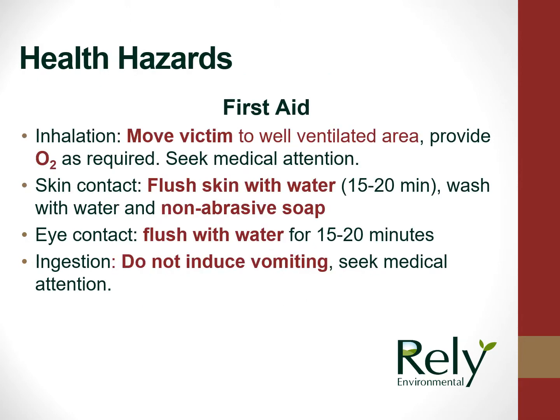If an acute exposure does occur, the recommended first aid is usually to move a victim of an inhalation exposure to a well-ventilated area and provide oxygen as required, to wash the skin for 15 to 20 minutes for skin contact exposure with non-abrasive soap, to flush the eye for 15 to 20 minutes for eye contact, and for ingestion, never induce vomiting. Instead, seek medical attention.